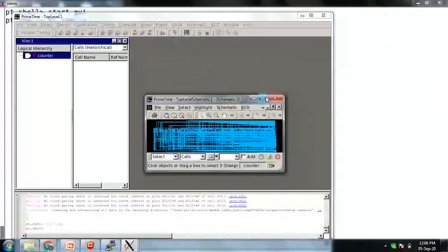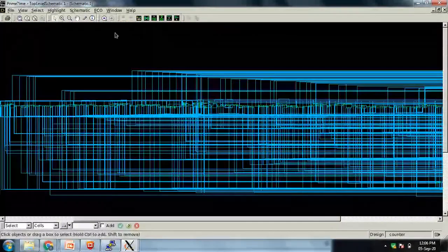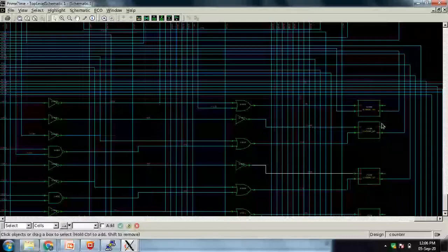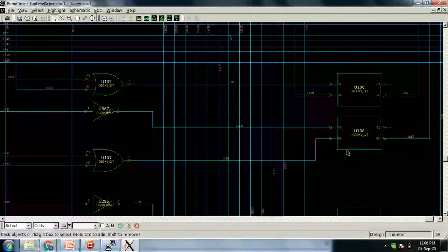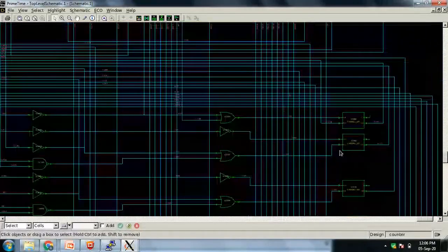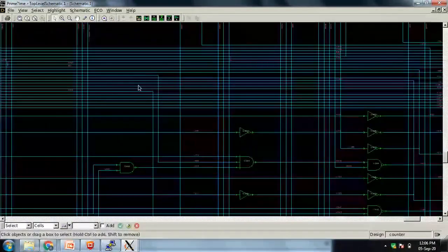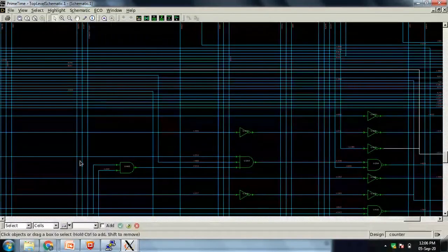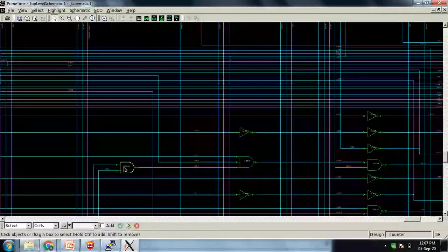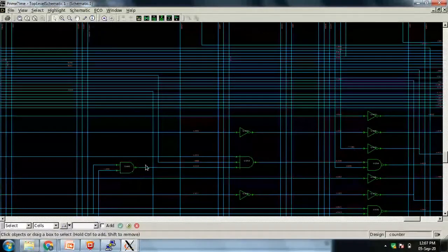See, this is the circuit, a big circuit actually. This is a circuit that I am showing you in the demo now. So some counter, some big counter. So you will have some input ports and you will have some output ports here. You can see flip-flops will be sitting here, right? And some gates are all there. What I was showing, right? These are all routing nets that are being routed, right? Cells are there. So net delays, cell delays, what I was talking about.